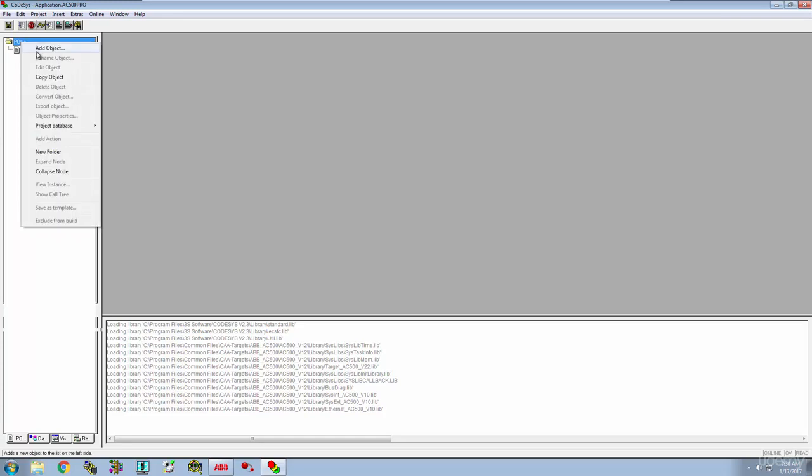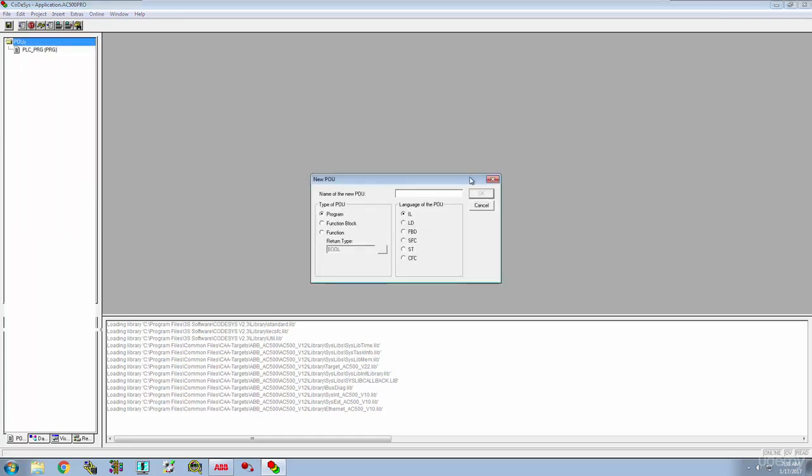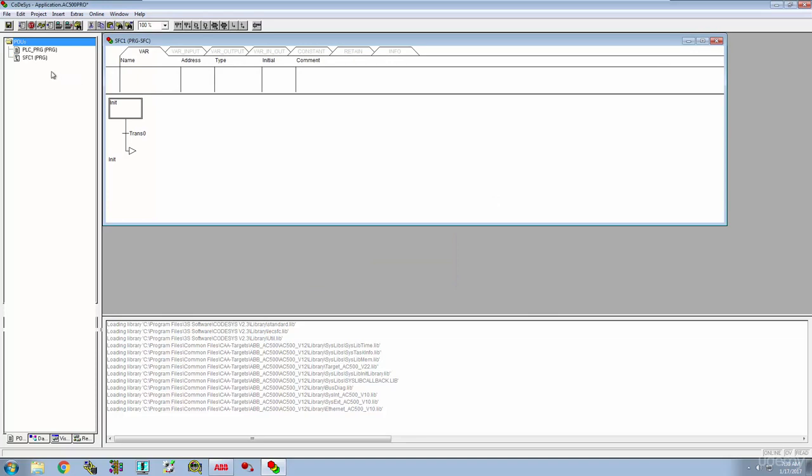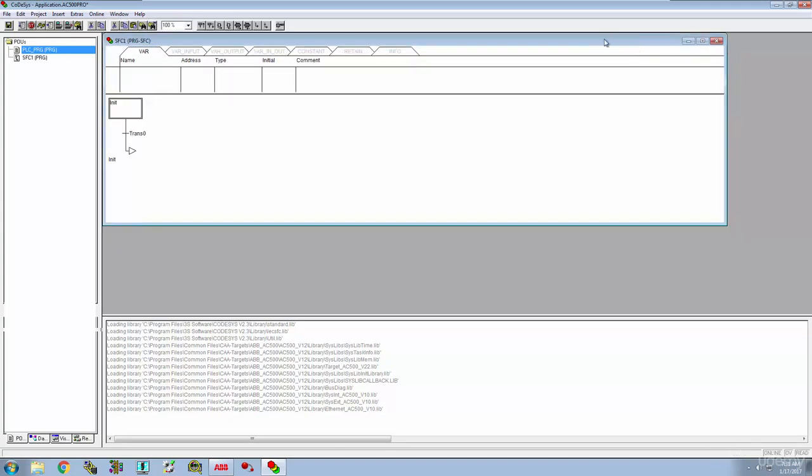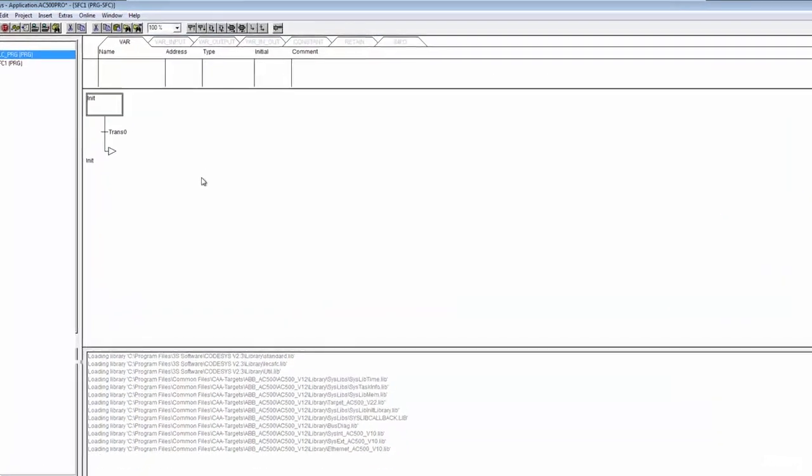Let's right click over here, add our project. We're going to call this guy, of course, SFC1. Let's make sure that we're defining an SFC. Hit OK. And then let's come back over here into our PLC program and make a call for that. So SFC1 semicolon. Then we can close that, maximize this one, and we're good to go.